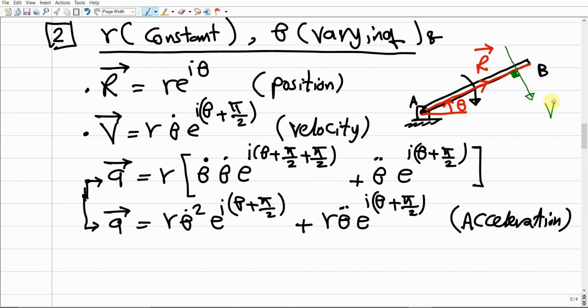So this gives us the position and the velocity vector, and the velocity vector goes in the same direction as the rotation, the same direction as omega, because there is theta dot here, which is omega, the angular velocity of the rotating link AB. So what does it mean? It means that we already have a shift, or a difference, between the direction of the velocity and the direction of the position vector by pi over 2, which is already shown here. Make sense?